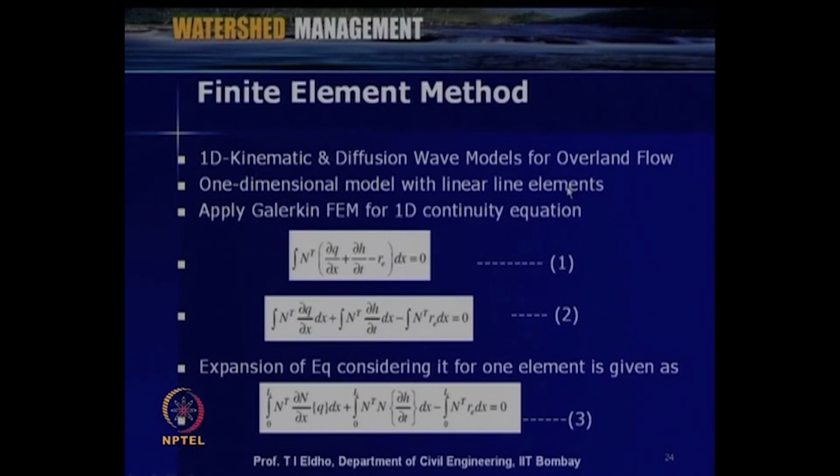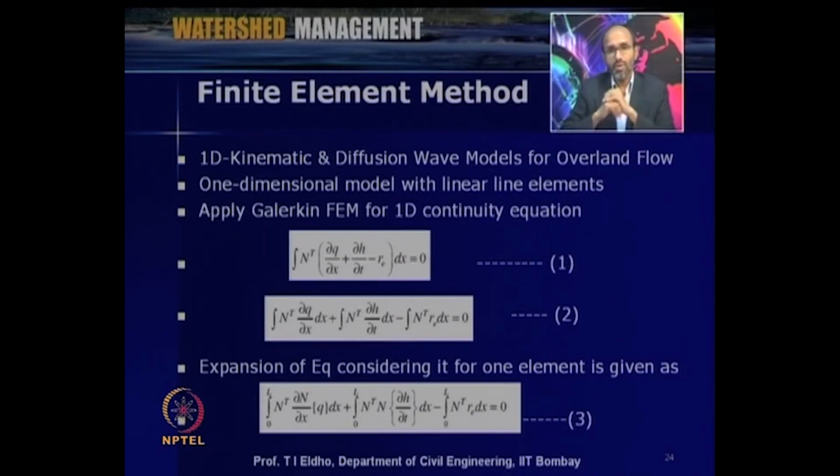So, then the next method I would like to discuss briefly is the so called finite element method. Here we again use the kinematic and diffusion waveforms of overland flow to demonstrate the finite element scheme. We have already seen the governing equations as far as the kinematic wave scheme is concerned: the continuity equation and the momentum equation, where for the kinematic waveform S0 is equal to SF.